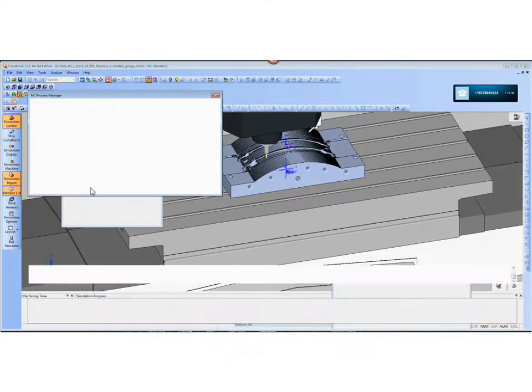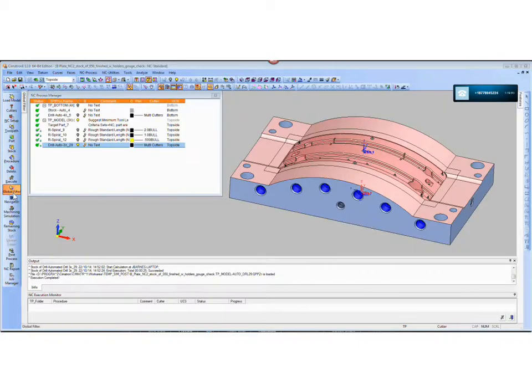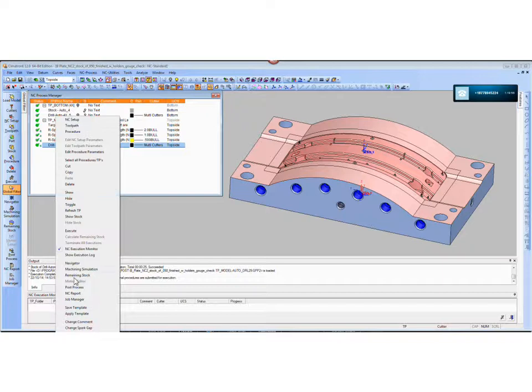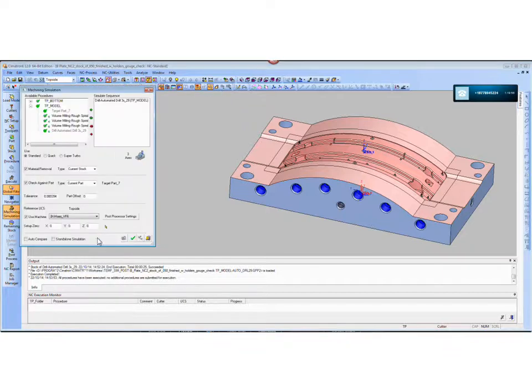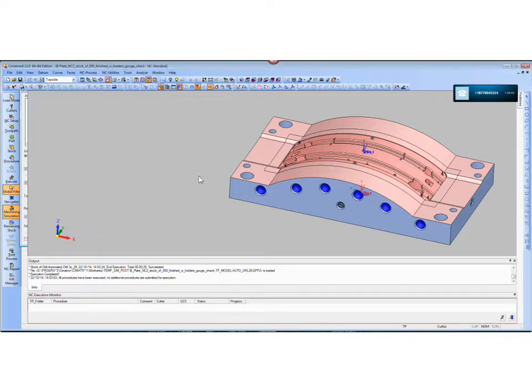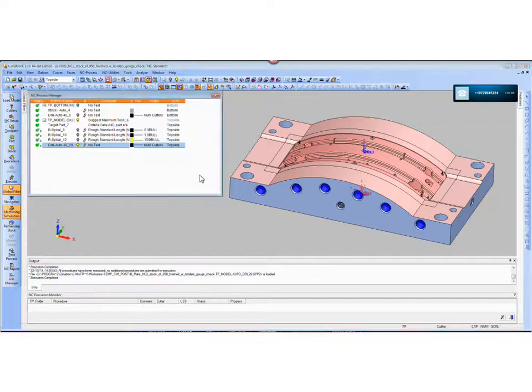I want to set the color to be unique for each tool, because it really shows nicely where the circle milling left off, where the center drilling leaves off, the pilot drills, the full depth drills. It really helps to illustrate everything really nice.